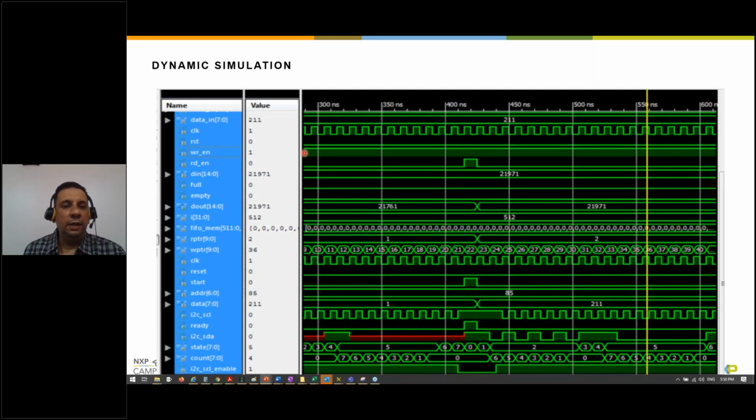In this slide, I just copy pasted one of our design signals. This design could be any design. What you need to do is run the simulation with specified options to enable the waveforms. Those waveforms can be loaded into the simulator, and each and every signal inside the design, and also to some extent inside the verification, can be loaded into the simulator window, and you can check the expected behavior of that.